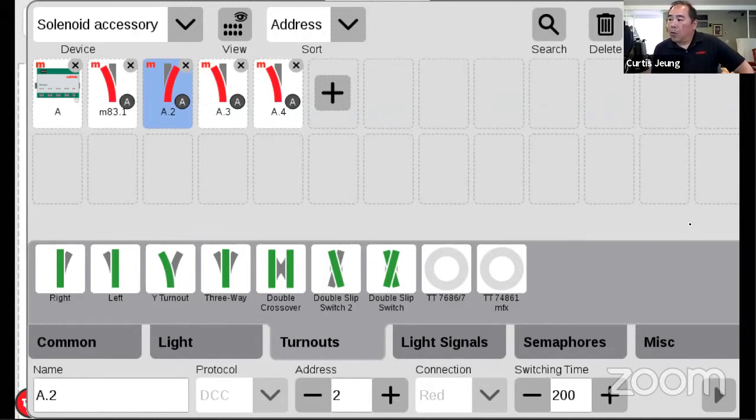So what happened there is I believe the articles they added were not MFX devices. So in other words, they added an old turnout signal or an old turnout decoder to like address 3, for instance. And address 1 and 2 were available. So the M83 took those addresses and it added another one at 3 and that duplicated addresses.